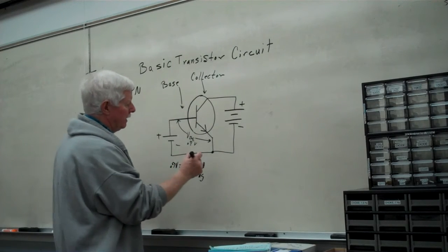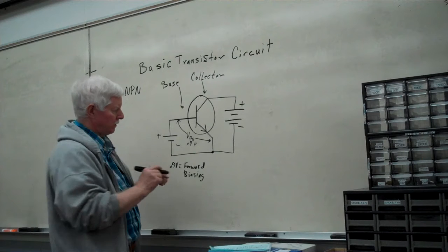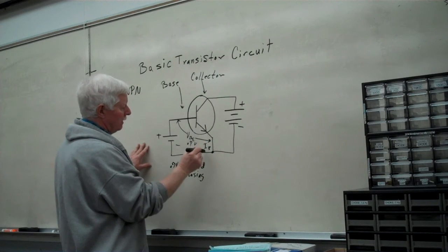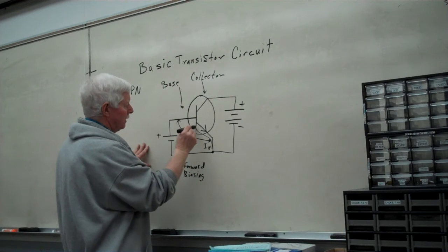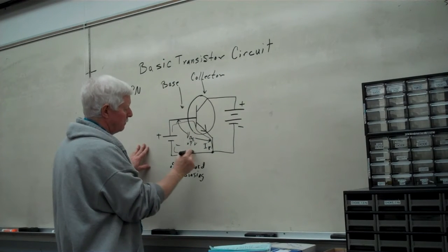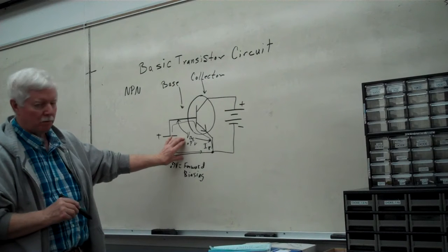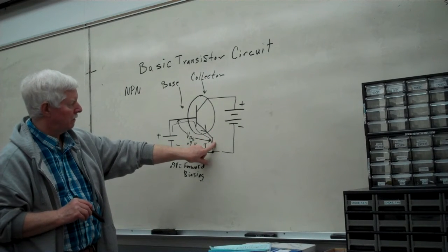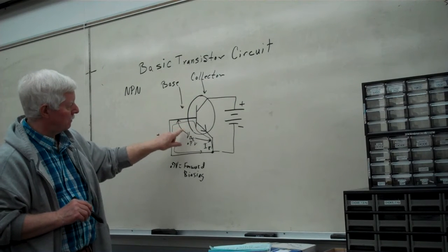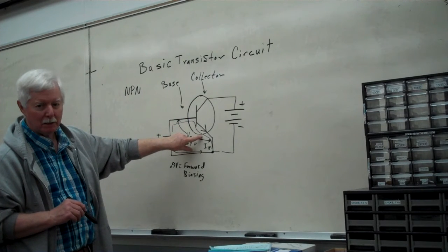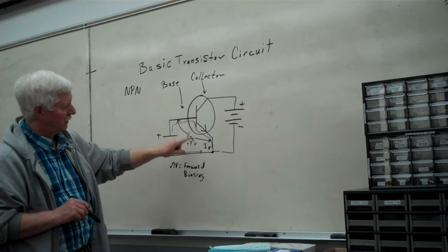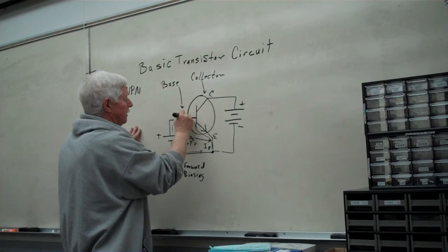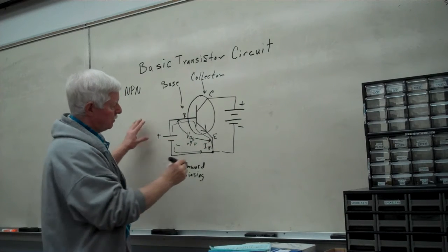So the very first one, it's actually got two currents. One's called the base current, and that's flowing through the transistor. It's going this way, back around, comes back into here. We call this the forward biasing loop. The reverse bias loop is actually between the emitter and the collector. So once the forward biasing has occurred between the emitter and the base, we can now have emitter to collector conduction as well. So it's going to go this way.